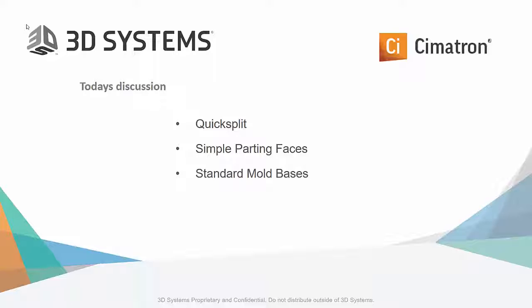This video will focus on separating cavity and core faces by using quick split, creating simple shutoffs, parting lines and parting faces, and we're also going to work with a multi-cavity situation involving standard mold bases from catalogs.